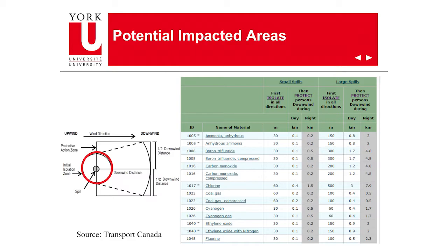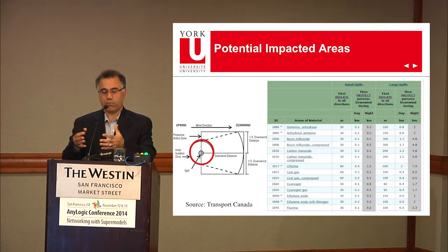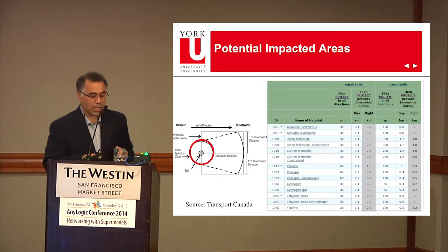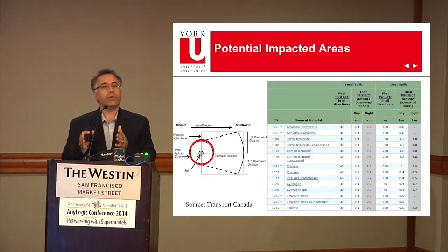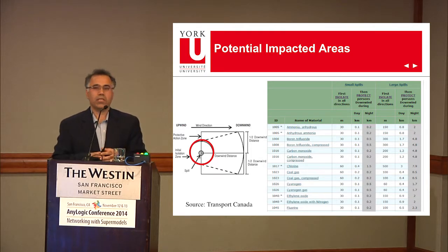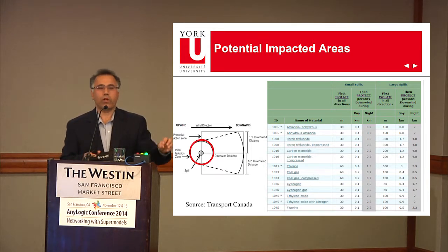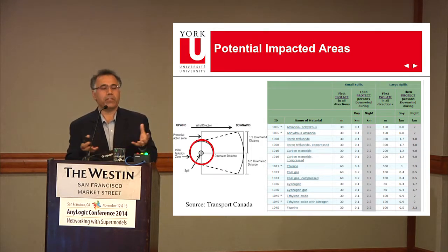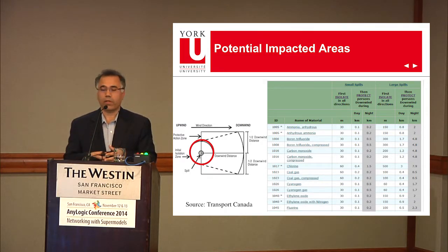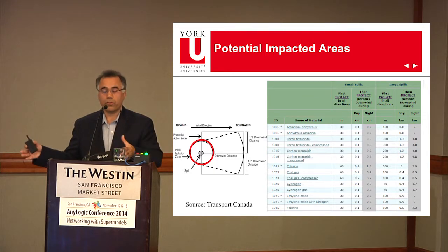The Government of Canada, same as the US, has standards for how much would be the exposure or impacted area for different types of hazardous materials, whether it is daytime or nighttime. This is for major spills, because we are not looking at smaller spills where normal emergency operation can take care of. But these are for larger spills where distances are usually high.